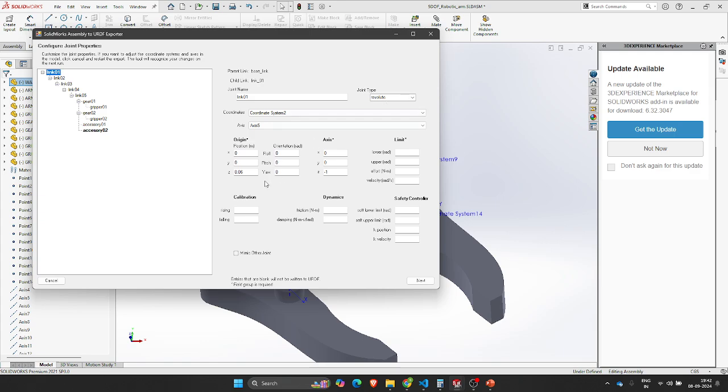Yep, it is Revolute. And do you need any effort in order to make sure that these things move? You could always add the effort and velocity. That's up to you, and you could even add dynamics as well as the damping. You could do that. We could go for link 2, Revolute, and everything is proper.